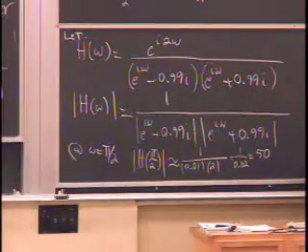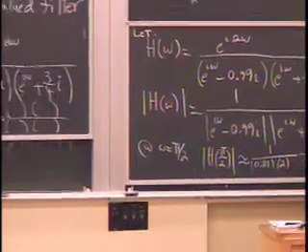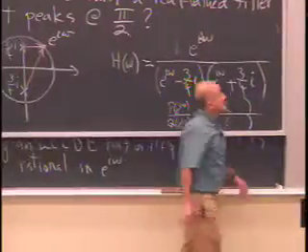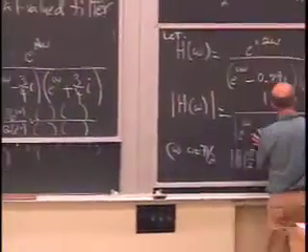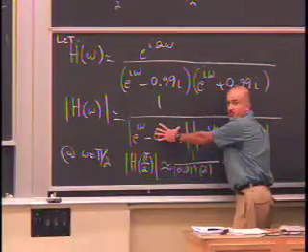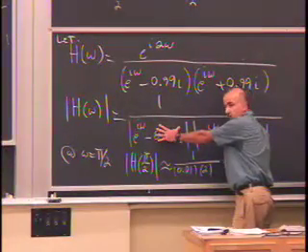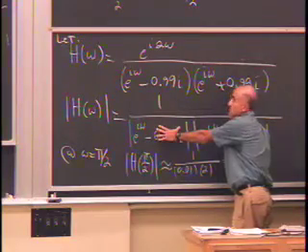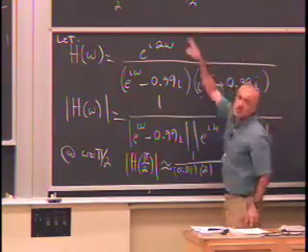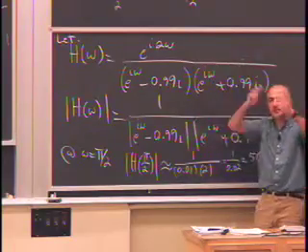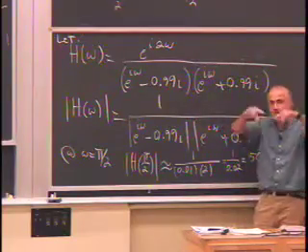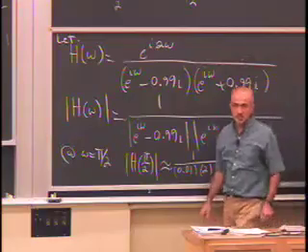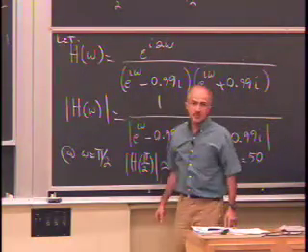And the same story when you go down here. As these x's move away from the unit circle, the nonlinear multiplicative effect of these two magnitudes in the denominator makes it more difficult to determine where the peak is exactly, at least visually. So those peaks won't be exactly at pi over 2 and minus pi over 2. They'll be roughly in that neighborhood. But the point is you get peaks in the mid-band range. It'll be a bandpass filter.